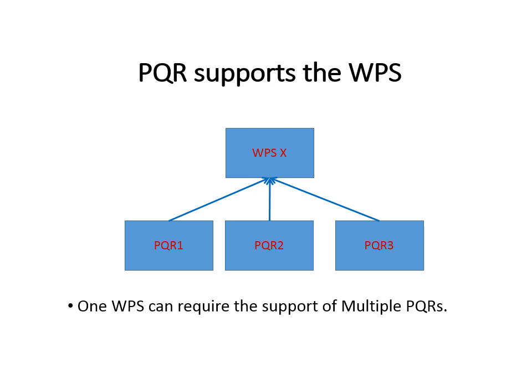Well, let's say a customer comes along and says, we like your WPS, but we need you to have some documentation for impact testing. So then we go do another PQR with the same materials, and we send it to the lab, and we get impact testing done. So we add that, but that's a different PQR. And then let's say there's a third variable that they want us to test, corrosion resistance or something. So we write a third PQR to help support our WPS.